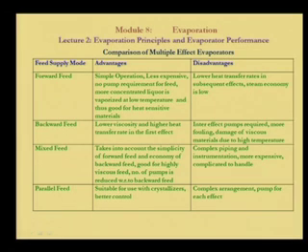But backward feed has lower viscosity and higher heat transfer rate in the first effect, and it is a lower heat transfer rate in subsequent effects, and steam economy is low in subsequent effects. But in backward feed, inter-effect pump is required and more fouling.